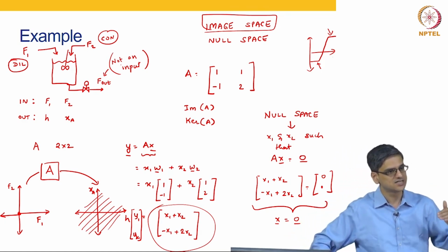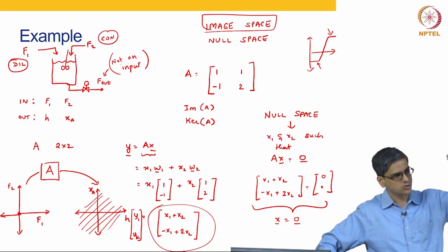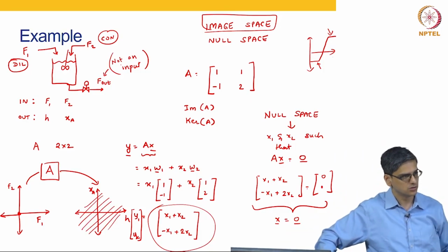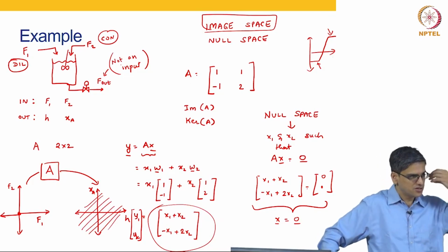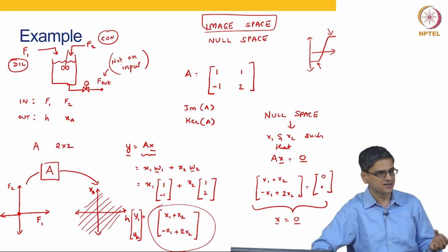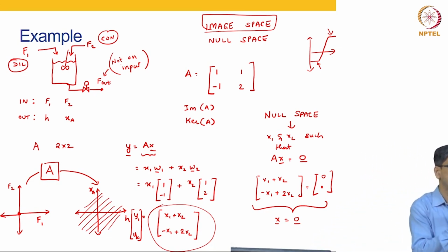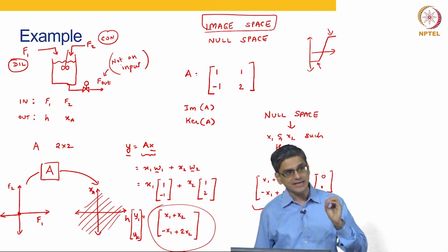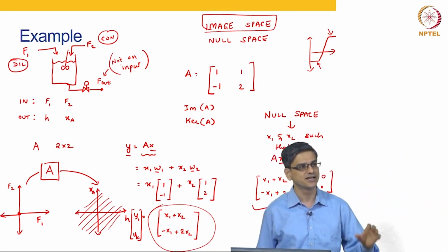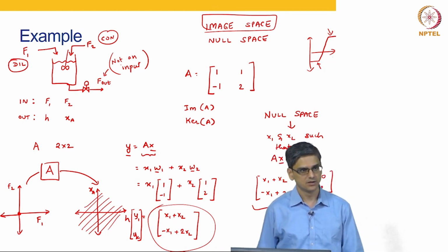You will say that beyond 0.2 or minus 0.2 your linear assumption itself is not going to work. So, when you are making a mental model of it, think only in a very small vicinity of where you are operating. Do not think globally. Very good question, extremely good question. And this is a constraint when you are using linear control.